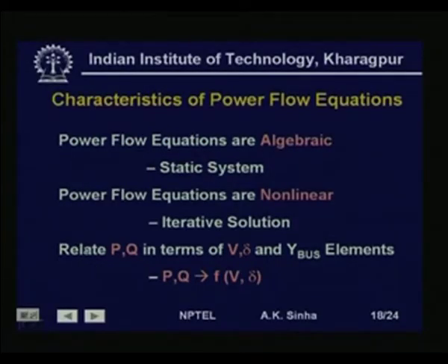Since these equations are non-linear, the general procedure for solving them will be an iterative solution procedure. So, these power flow equations relate the PQ injections at any bus bar in terms of V and delta, the voltage magnitude and angle at various bus bars, and the Y bus elements. That is, PQ are a function of V and delta.